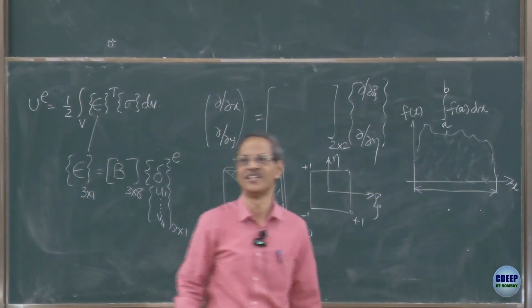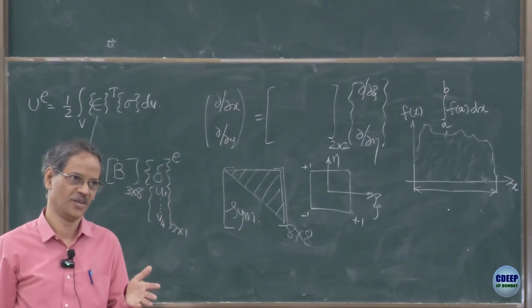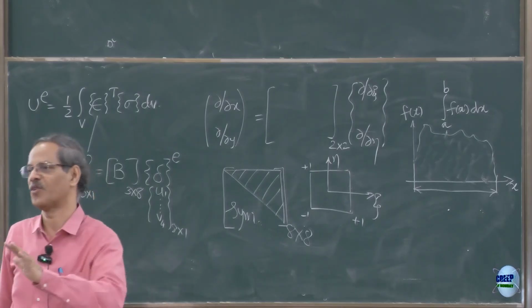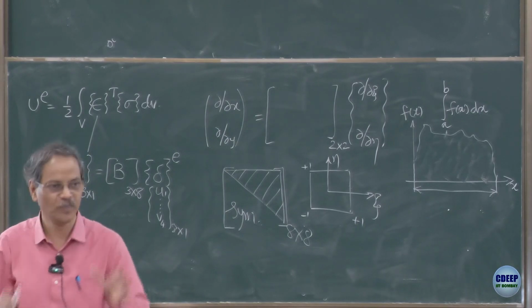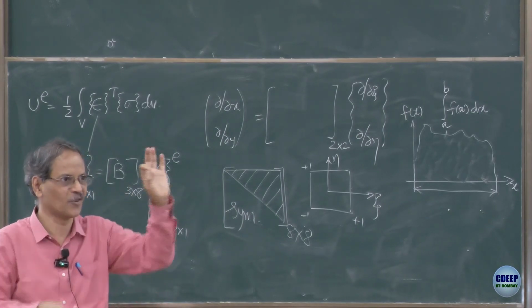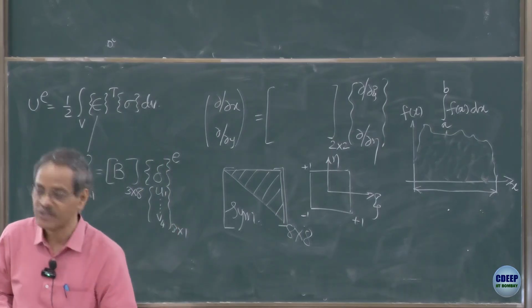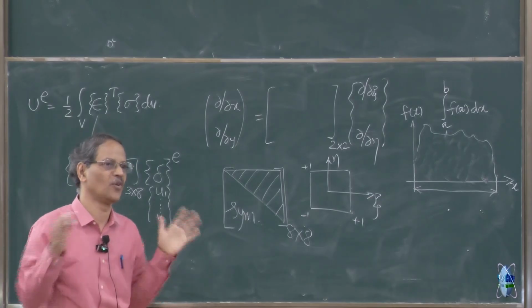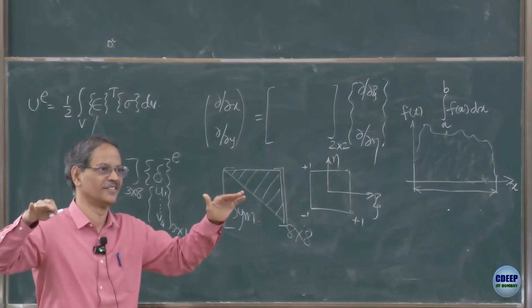correct? The area under this curve I need to estimate, and because I do not have an easy looking expression for f of x, like in this case f of x would actually be the B transpose D B matrix coefficient. So, what I am going to do is, I would think that curve f of x is some known curve.